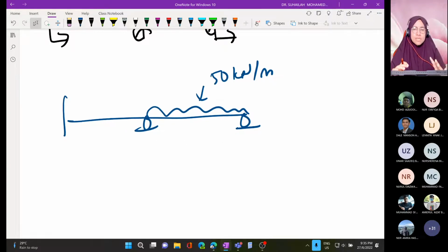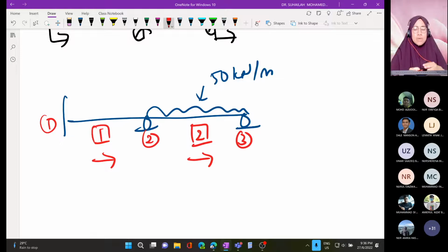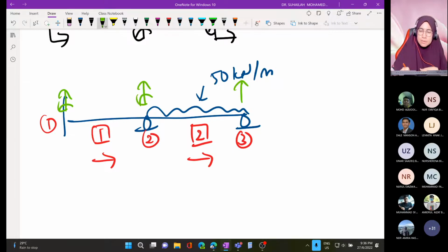Most important thing when you want to analyze a beam, of course in a beam we don't need to put coordinates, and arrows are not needed. What we need here is the node number, the element number, and the arrow, understood as going in the right direction, because we refer to the appendix. And label the degree of freedom. The degree of freedom must be put correctly.